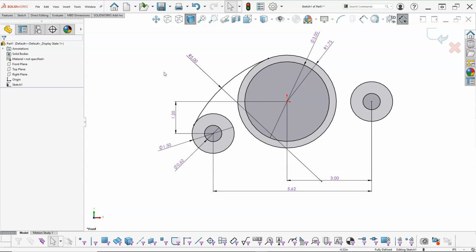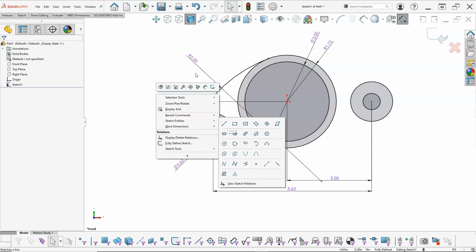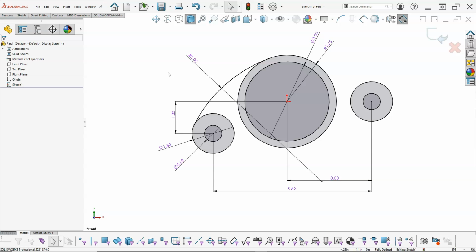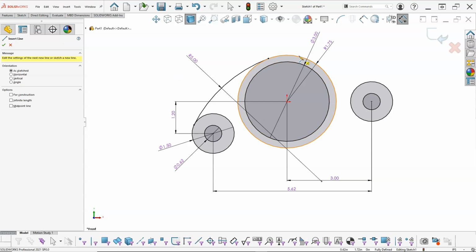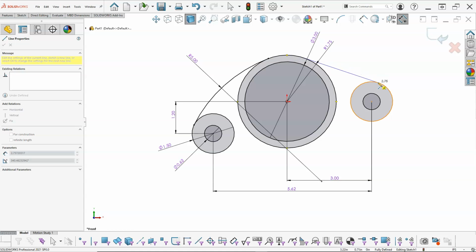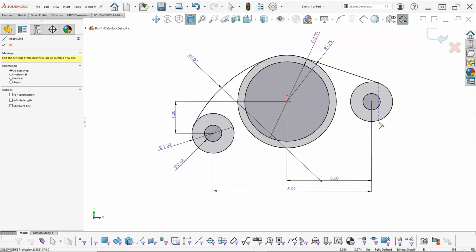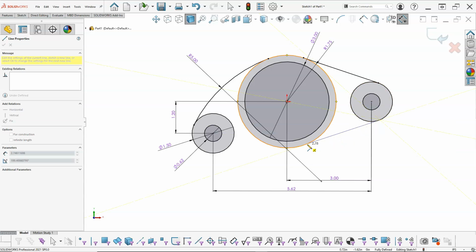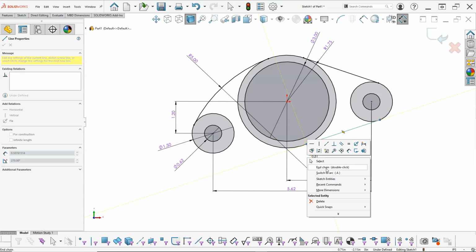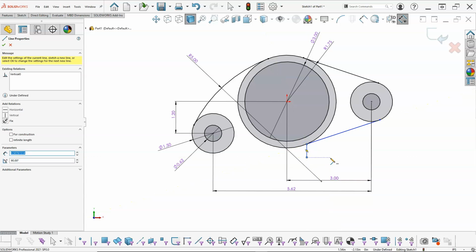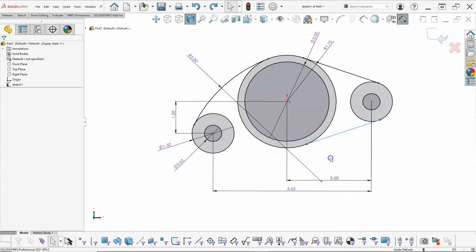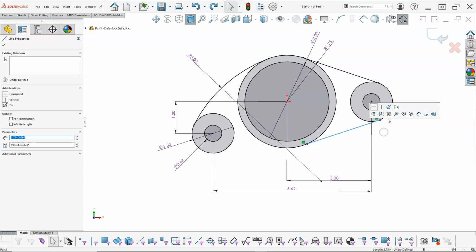All right, so we can go back up to the sketch and pick the line. We can right click, go to sketch entities and pick the line, and then as we get a little bit more comfortable, we can do the L on the keyboard, and that'll take us right into the line. Okay, and then I need to escape out of that. I think if I had hit, well, let's see. And again, there's habits that I've developed that, all right, so we're in that click click. If I right click, switch, or in chain is double click. All right, so gave me the extra one. I'm better off just hitting the end of the geometry.